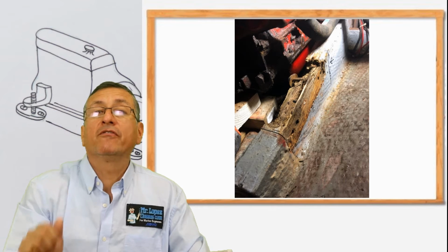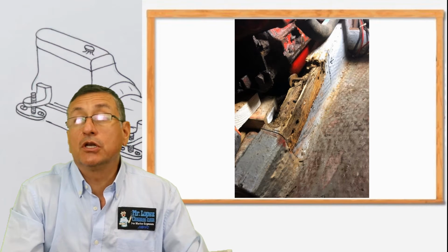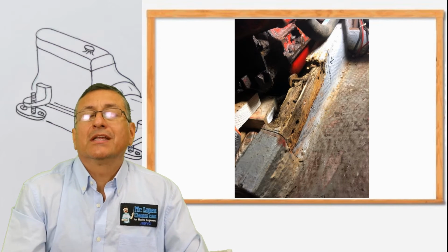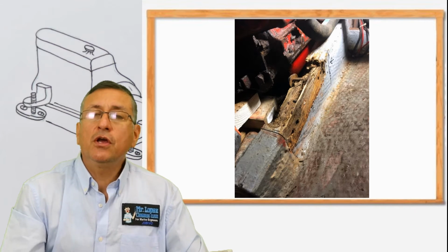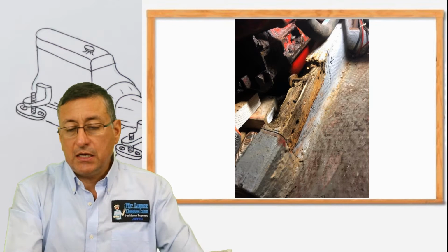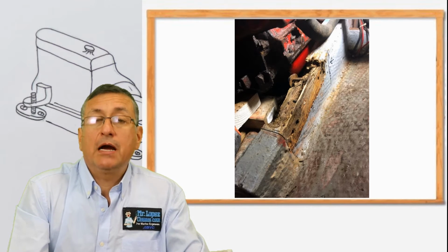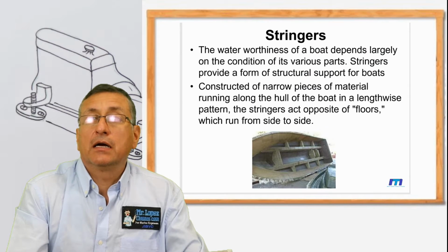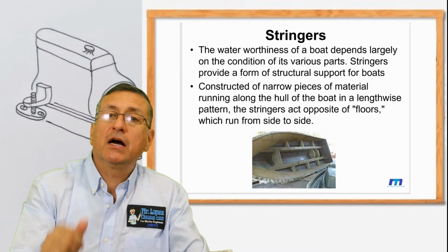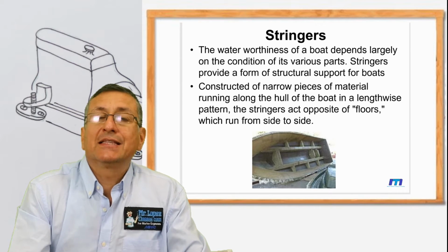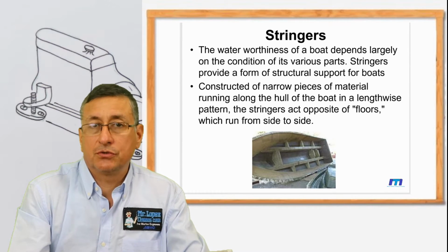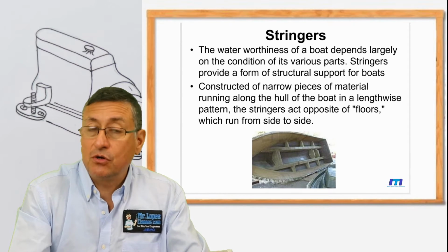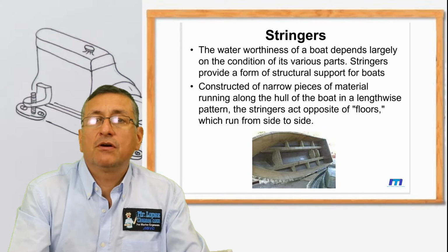And you have a lot of inconvenience, vibration, noise, and a lot of problems because the stringers are in bad condition. For that reason, my recommendation when you buy a boat is to ask a professional in order to verify if the stringers and the transom are in good condition. Because if the stringers are damaged and the transom is damaged also, the price of that boat is zero.